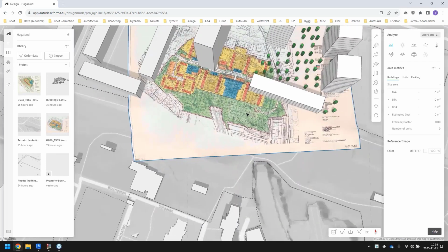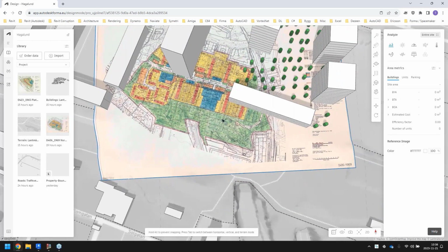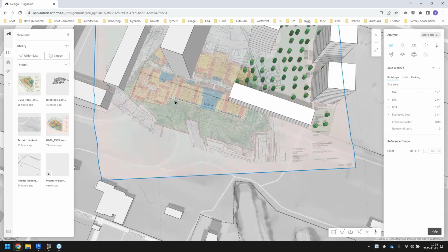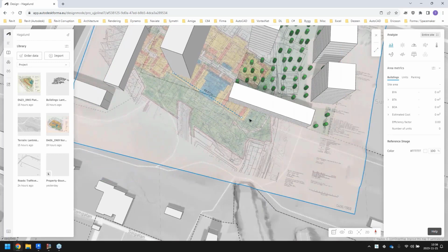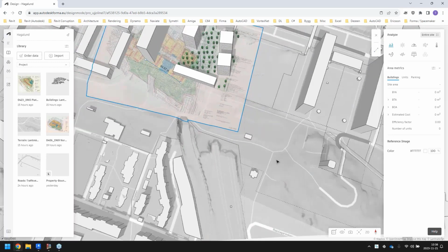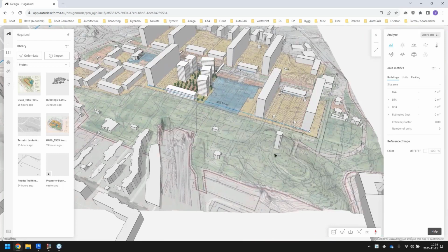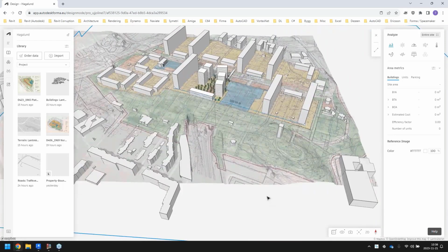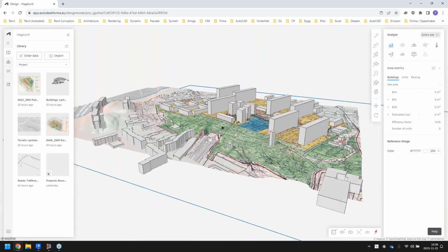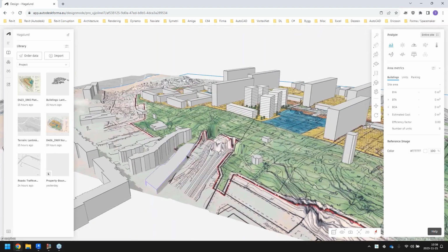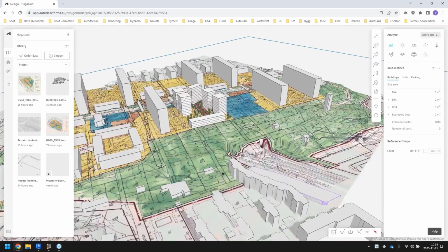So I actually know that I'm not overstepping my bounds or something like that. Let's just rescale this one. So I will select that building, this building, and just scale the image so it fits the existing conditions on site. Just pull that one out, snap it over there, and then I have an image draped over my topography with the official